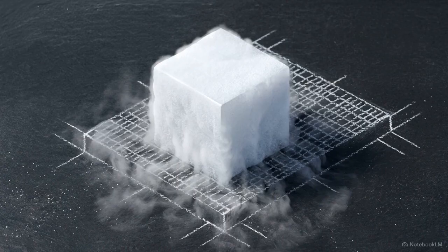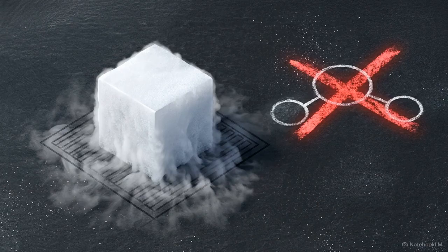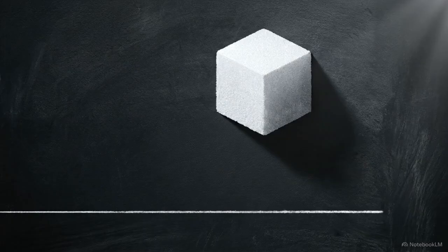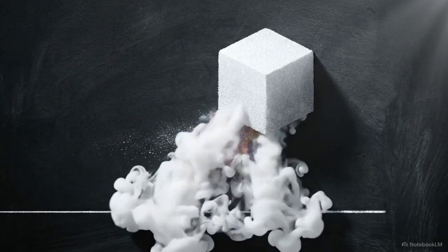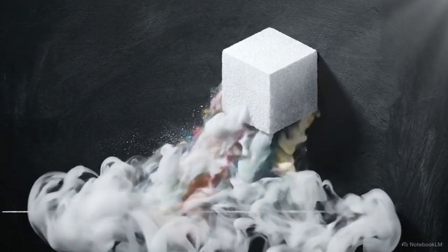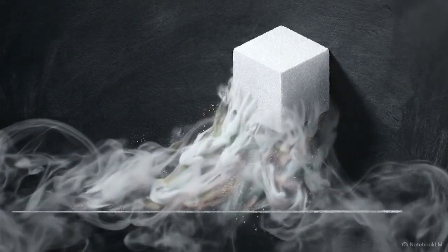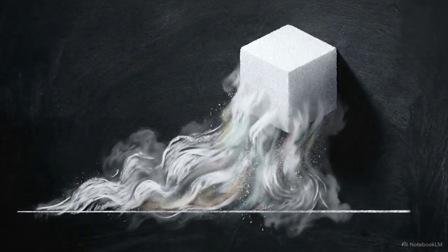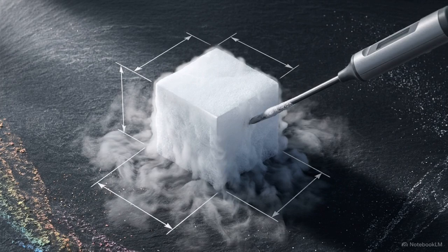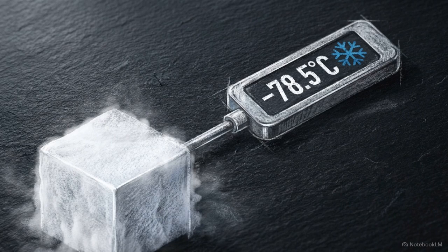Let us advance to our third method. Dry ice is explicitly the solid state of carbon dioxide. It is not frozen water. It cools through a thermodynamic process called sublimation. As you can see, the solid transitions directly into a gas without ever entering a liquid phase. For mechanical engineers, dry ice provides a critical specification. During sublimation, it maintains a steady, extreme temperature of -78 degrees Celsius.